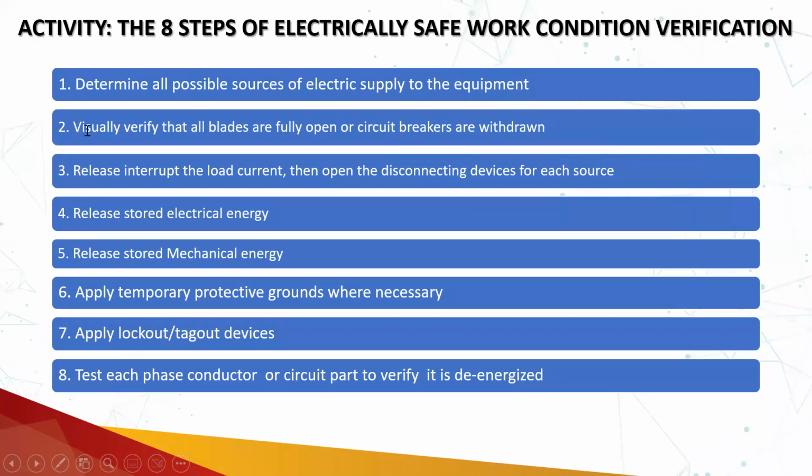Then visually verify all the blades are open. No, up till now I have not performed any job. So release, interrupt the load current, then open the disconnecting device for each source. Yes. So the correct step is 1, 3.